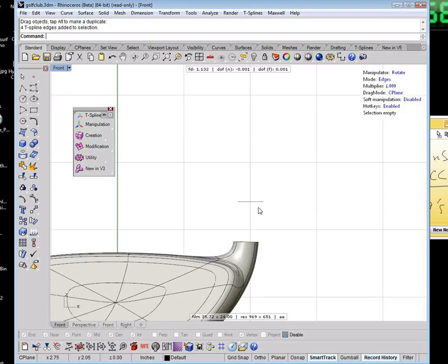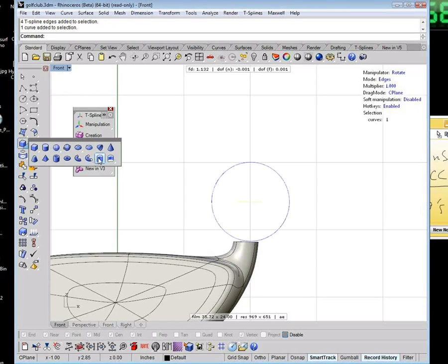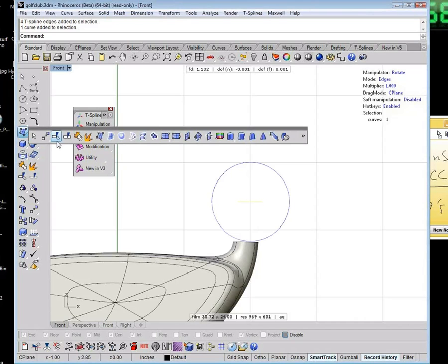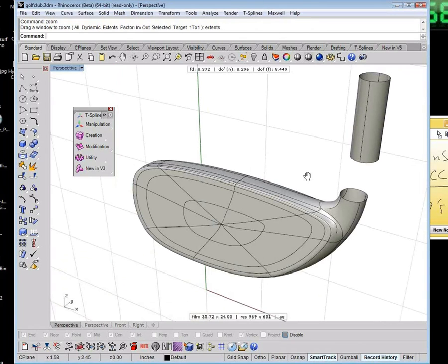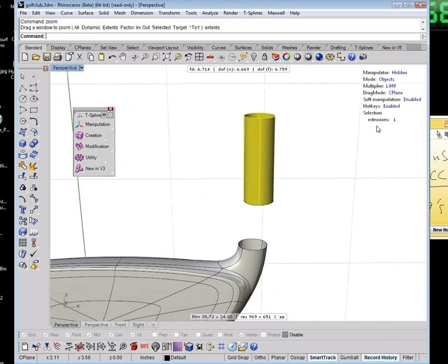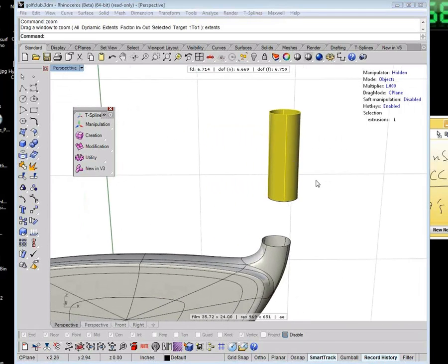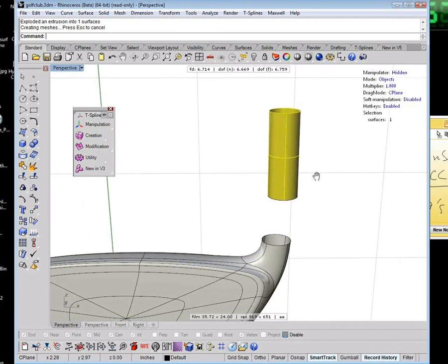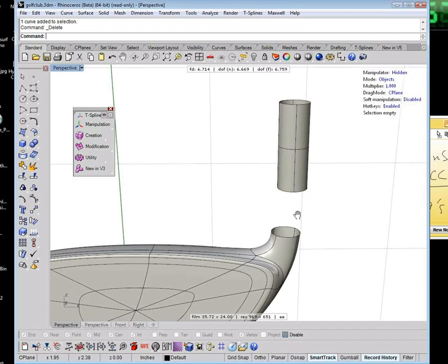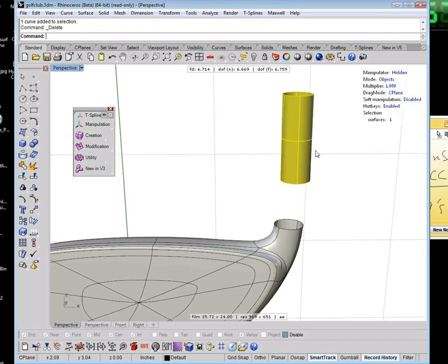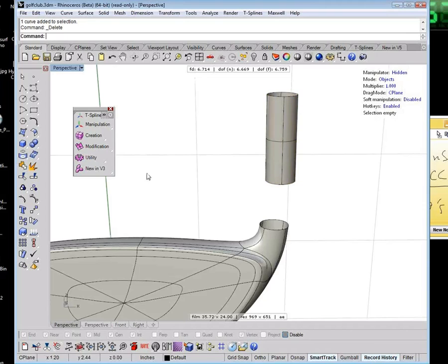All right. So if I just take this object and use the Rhino extrude, I just get a Rhino object. If I bring this up, you can see it's showing as an extrusion. In version 5, there's a new object called an extrusion, and they've been causing some issues. That might have been what the problem was before. If you explode them, it turns them back into surfaces. So this is just a NURB surface, and I can use the Rhino blend surface